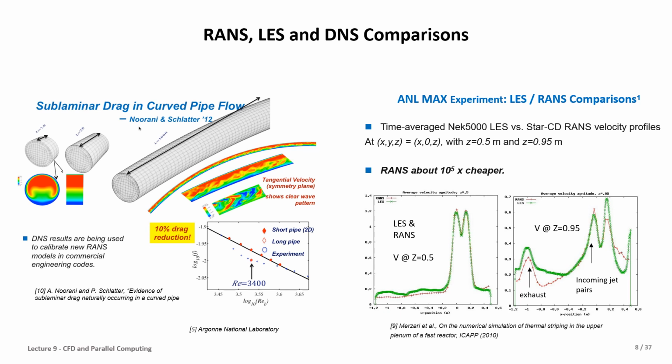But when we look at the second one, which has different coordinates, the result from RANS at some points provides a different result. And these differences sometimes impact the design, and sometimes it's required to calibrate the RANS simulation with the result from LES or DNS.